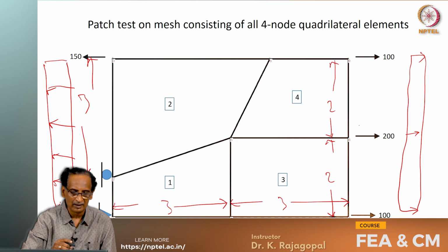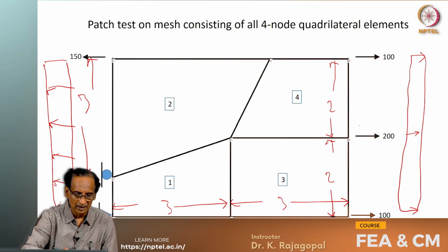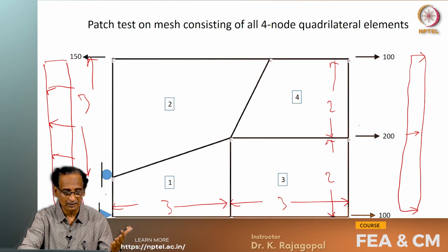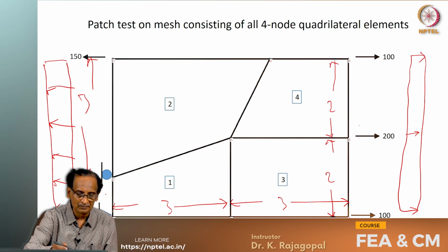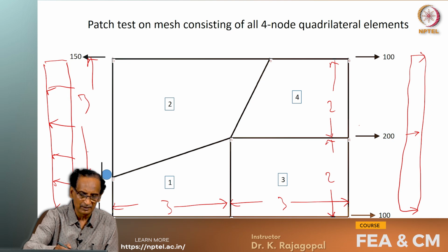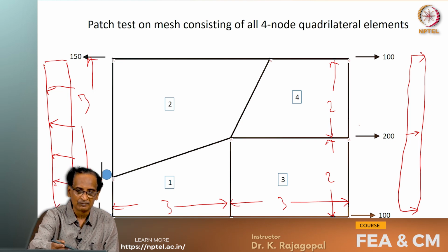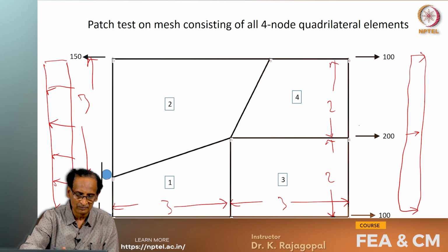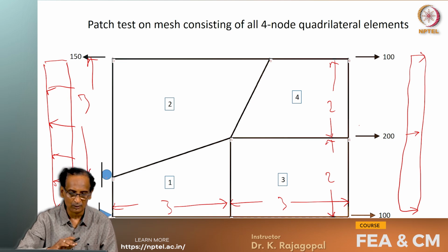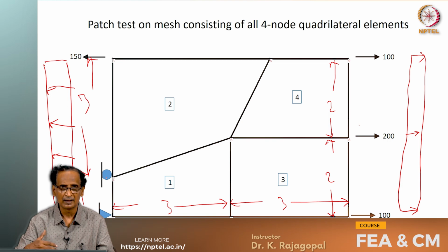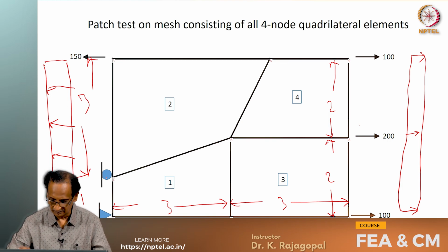Okay. And then for element 1, both of these nodes are fixed in this lateral direction, so there is no force, and there is only force on element 2, and this pressure of 100 is acting on a length of 3. So, it is totally 300, and we distribute half of that, that is 150 here at node 3 and another 150 at node 2, but node 2 being a fixed node will not have any load transferred there.